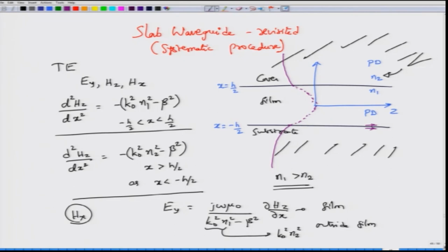And incidentally, this mode now will have what is called the TE0 mode. Okay. So, it will be a solution even when nu is equal to 0. The field is not going to 0 when you substitute nu equal to 0. Okay. The other higher order modes are equally possible. So, you might have the same kind of a decay constant, or you might have a slightly different decay constant out there, but then the field itself could be something like this, okay, and then the field would be decaying around in that manner, or maybe decaying in this case. Okay. So, outside it would still be decaying, but inside it would be a sinusoidal kind of a field.